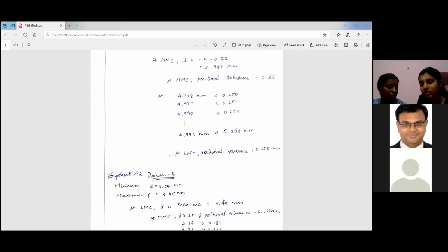Because those dimensions, the tolerances will be given separately in the drawings, like in the title box or somewhere in the notes, and then we'll mark the dimensions with a box. That is, for those dimensions, we'll be giving the tolerance separately.